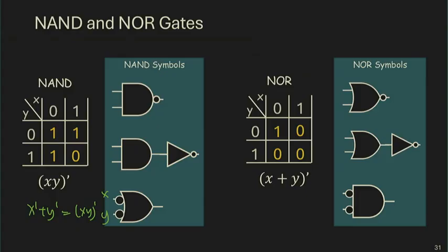And people call this bubble pushing. You can go from top to bottom by pushing the bubble, conceptually pushing the bubble backwards through the gates. In the meantime, it becomes a bunch of bubbles at the gate inputs, and you're also switching the gate between AND and OR. So push the bubbles through the AND gate, the gate becomes an OR gate. You have multiple bubbles. You can also think about bubble pushing in a different direction. Two gate input bubbles, you push them through the gate. This one becomes an AND gate. All the bubbles converge into a single bubble. So that's the bottom to the top through bubble pushing.